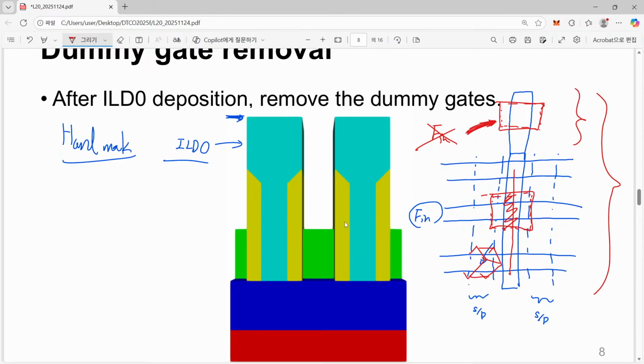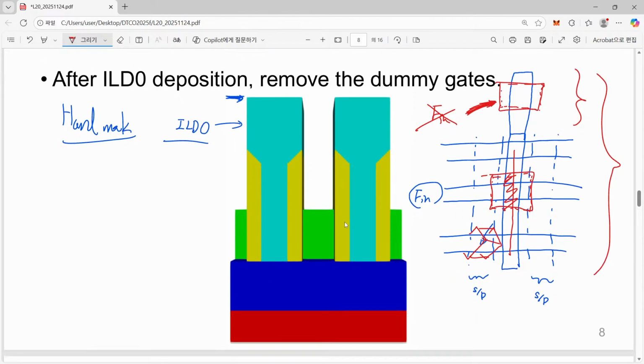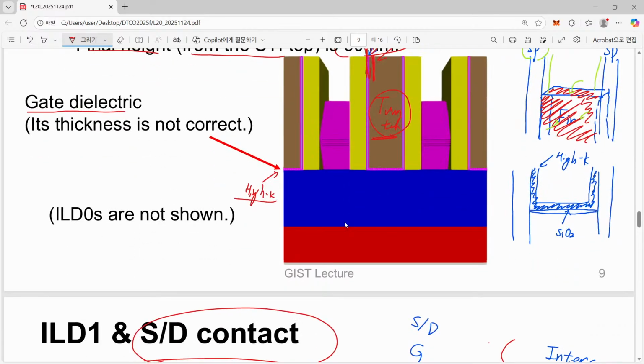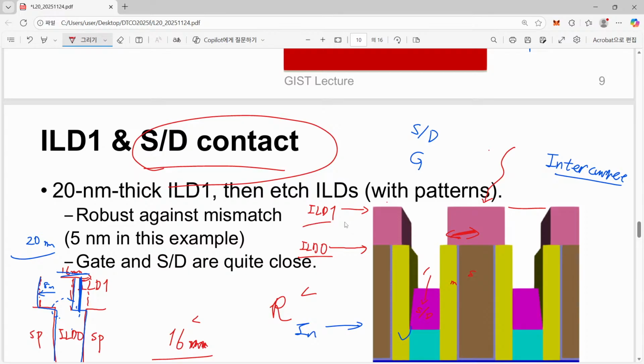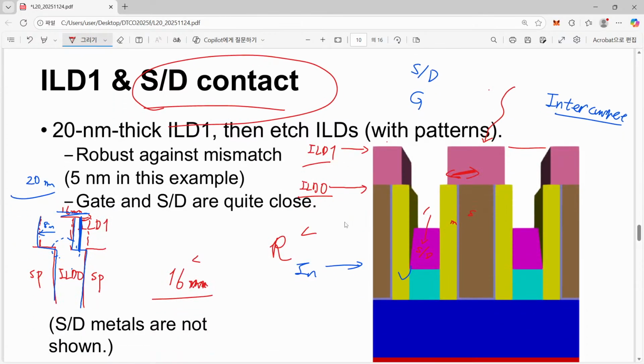So please understand that situation. So what we have done is, although we have considered just two layers, ILD0 and ILD1, intentionally, after filling this ILD0 with tungsten fill, people intentionally once again etch away this top part. This top part is etched, and intentionally we introduce silicon nitride. Then they are protected from this one.